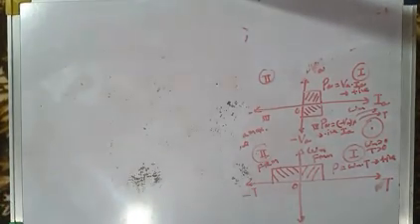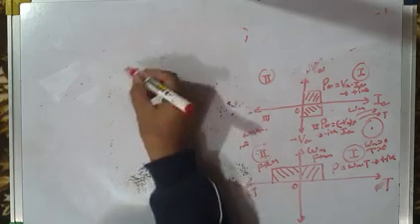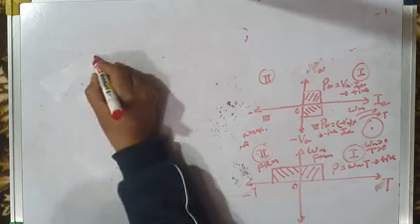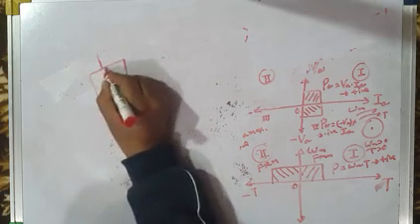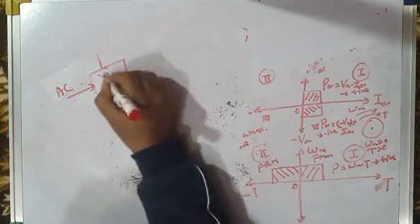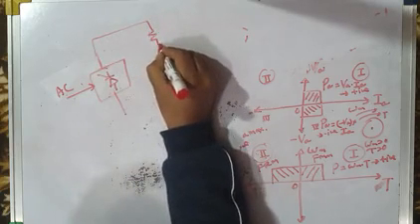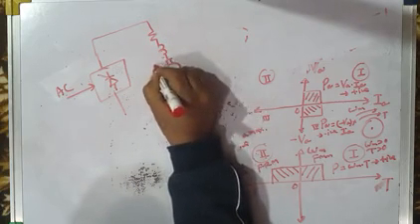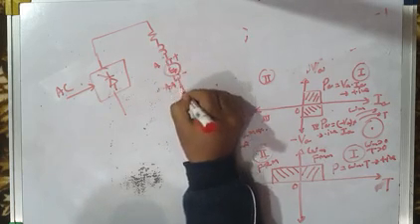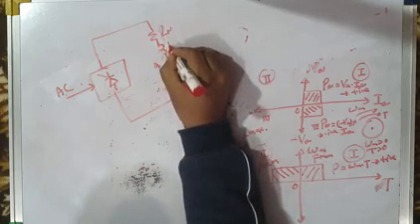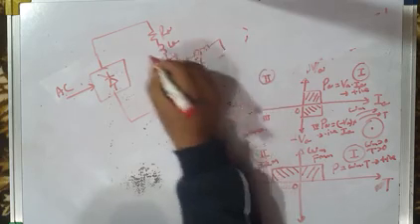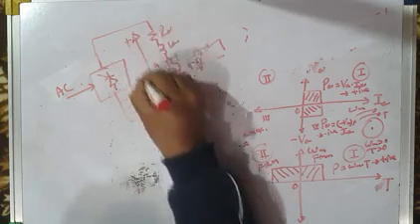Another way of understanding it is like this. You have to understand regeneration. Forward regeneration will take place like this also. Say for example, this is again your phase controlled converter, full converter of course, which is fed from single phase AC, and this is your motor, A, AA, and this is back EMF EB. This is armature circuit resistance RA, inductance LA. This is the field current IF, which is constant. This is armature voltage plus minus VA.